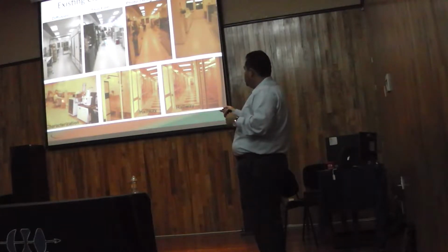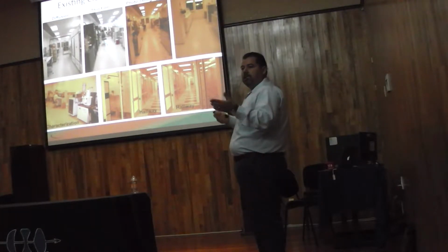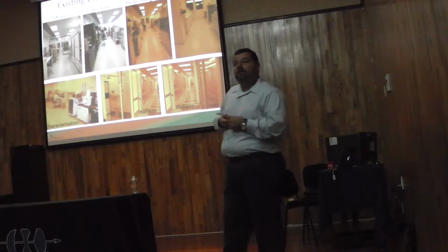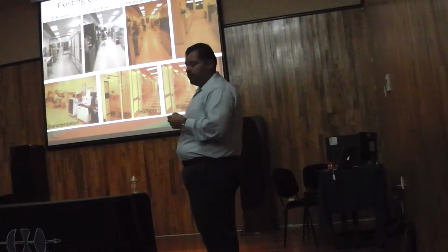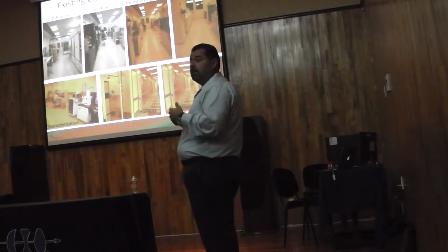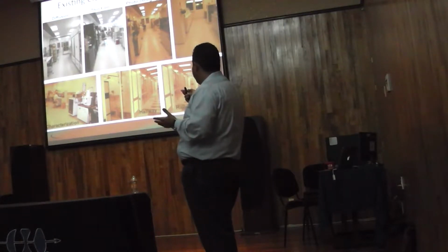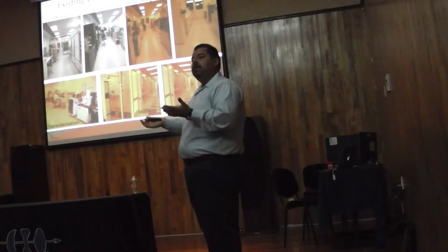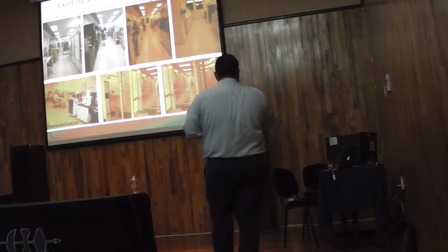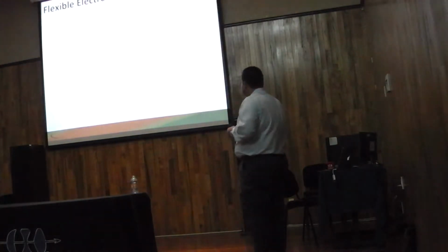We have also spectroscopic ellipsometry to look at thickness, if the film is a dielectric, for instance. So you don't have to go out of the clean room to measure some of the characteristics of the film, which is great because if you exit the clean room, then the film becomes contaminated. You cannot move it back in the clean room. So this is a good thing to have the characterization in there.